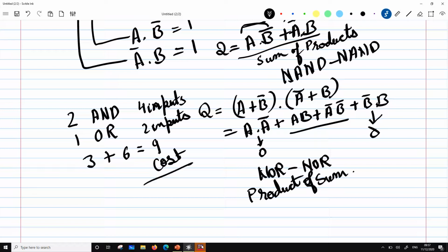The idea is to minimize the cost of the circuit, and we will come to why we minimize it. Because what we want to do is minimize the number of transistors, so that will be minimizing the gates, and then we are going to minimize the inputs, right? This has to do with something called fan out or timing, which we will come to later on.